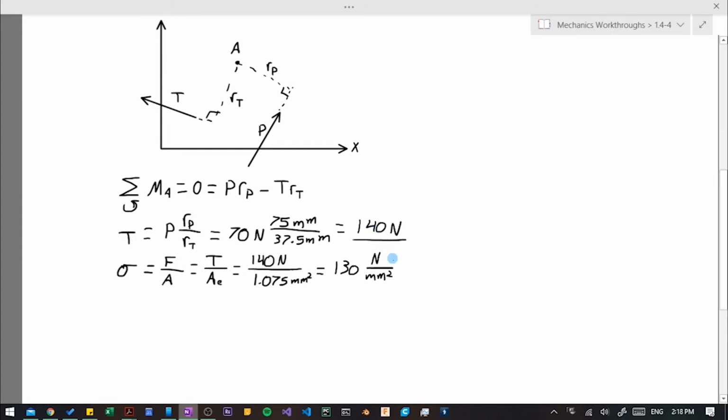One way you can think about this is that there are 1,000 millimeters in a meter. So if we multiply by 1,000 millimeters and divide by a meter, this value is equal to 1. Since we have millimeters squared, we're going to square the top and bottom of this, and it will still be equal to 1, so it's not changing our value. And this here, newtons over meters squared, that's pascals, which is what we want to convert to. And then, of course, the millimeters cancel out.